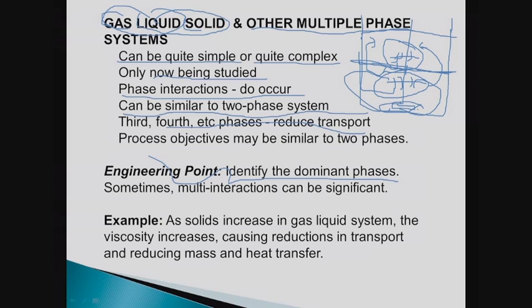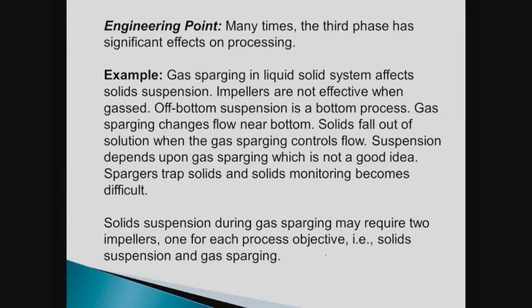Solid suspension will tag along. All right. And of course, as I increase solids in gas-liquid systems, the viscosity increases, which causes a reduction in transport, reduction in heat transfer, reduction in mass transfer. So the third phase often doesn't help much. Oftentimes, or many times, the third phase has a significant effect on processing.